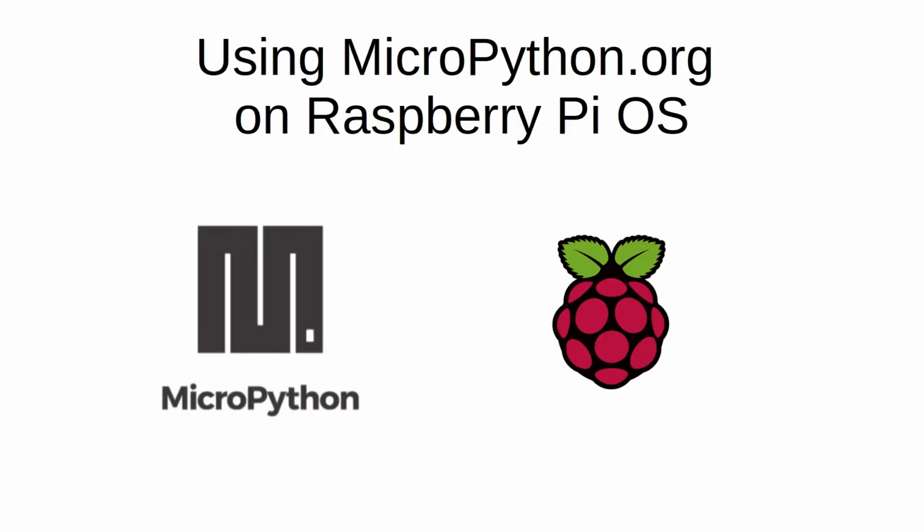I'm now going to show how you can use the upstream version of MicroPython. This is the version from micropython.org. It's designed for the Arduino RP2040, but is before the modifications that Arduino have made. I'm not sure what the differences are. It may mean there are libraries missing, but the code used in this example works fine on this. I've noticed one thing which is different, is that the version of micropython.org does not appear as a removable drive as with the OpenMV version. You can, however, save files using Thonny and using command line tools like ampy, so it's not a problem.